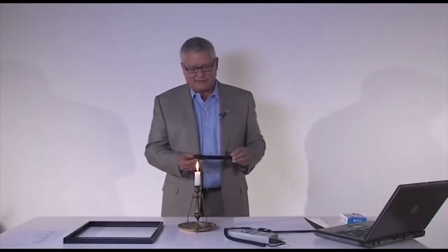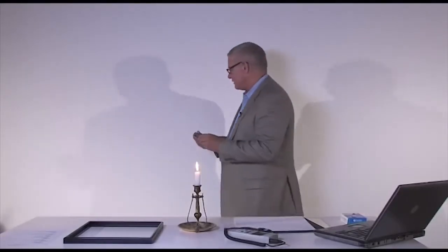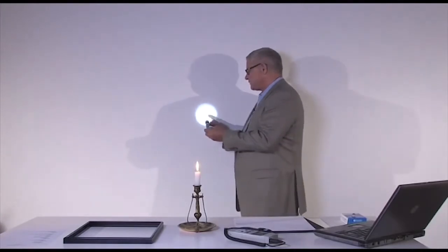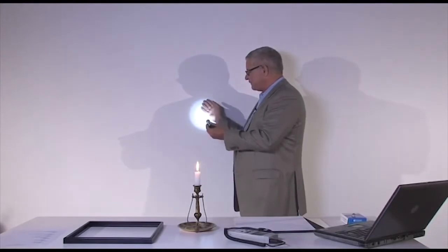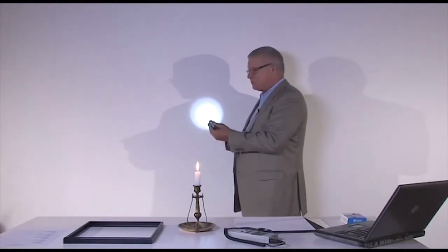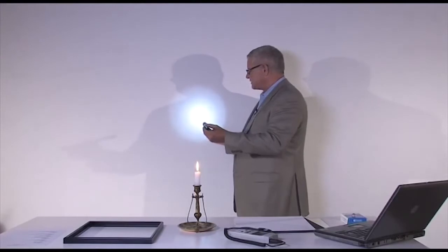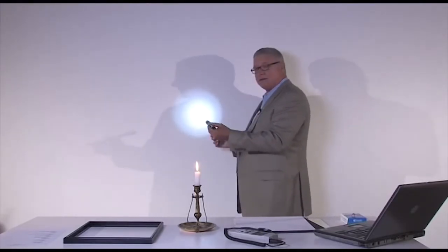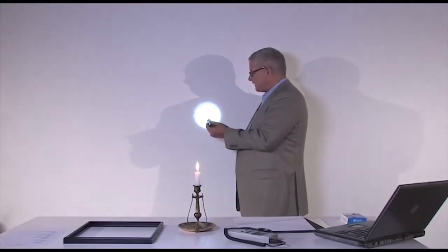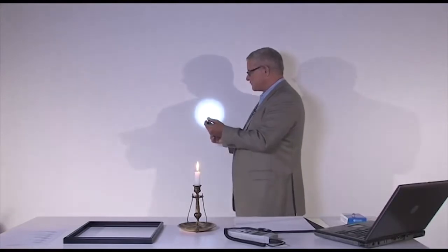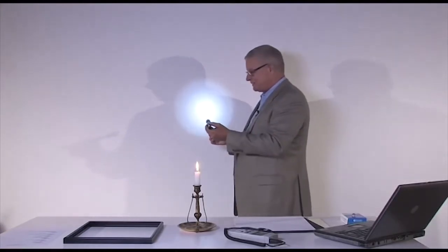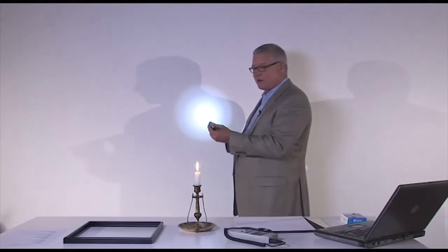There are 2 things that impact that density of light, and I can demonstrate them going back to my flashlight and looking at the wall. If we consider a circle on the wall, there's a certain density of light falling on the surface, the illuminance. As I increase the distance, you see that the light is actually covering a much larger area. Therefore, the density of illuminance, the foot candles, are being reduced as I increase the distance. This is called the inverse square law because it varies inversely to the square of the distance.